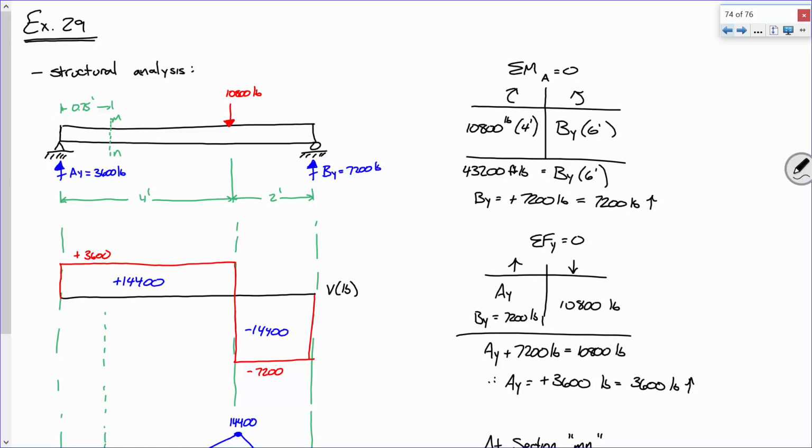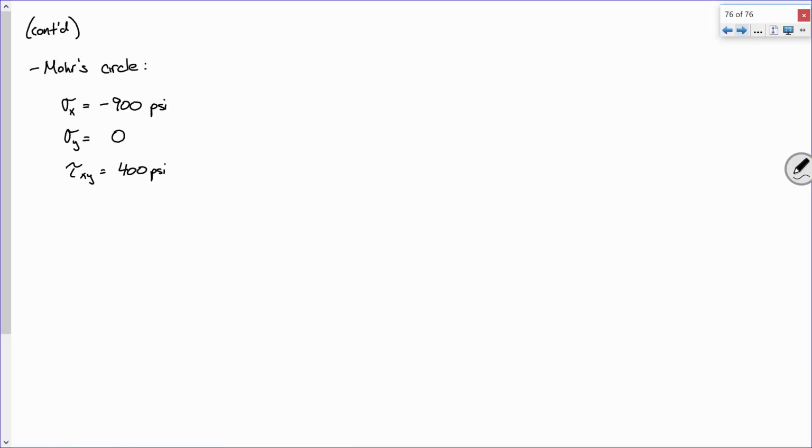I'm not taking this point. See, for a situation like this, the only way to generate stress in the y direction would be if I took a big C-clamp and clamped it right there and actually started pushing it. I'm not doing that. Do you see what I mean? Imagine what would happen if I took a C-clamp and started tightening it right here. What am I going to do? Sandwich that. You see what I mean? I'm not doing that, so 0. Or I could take it and yank on it, I suppose. Does that make sense?